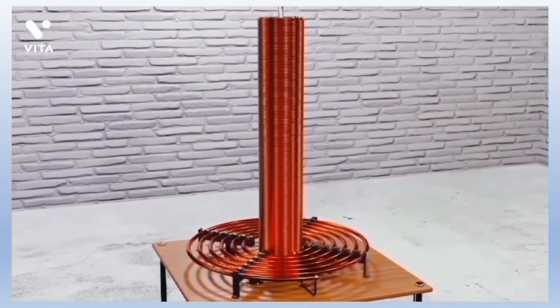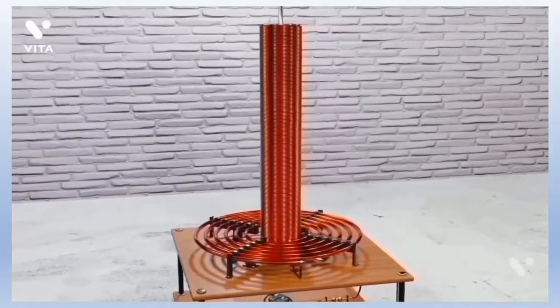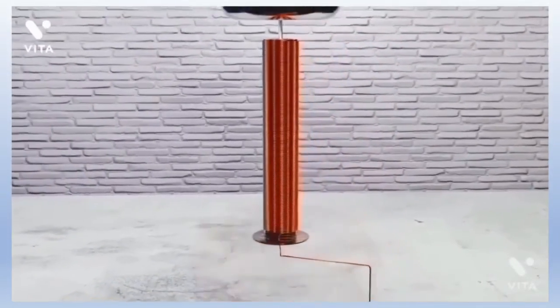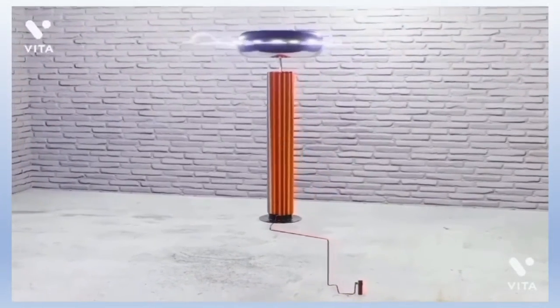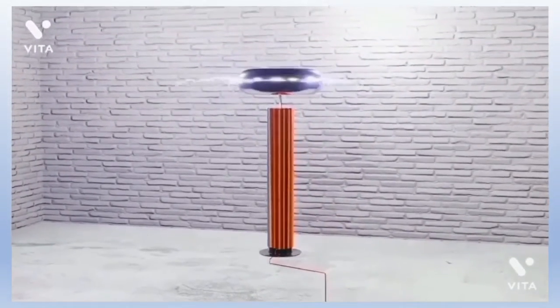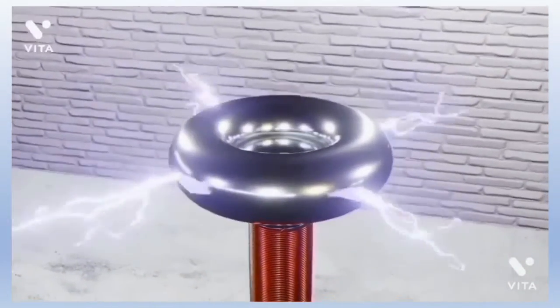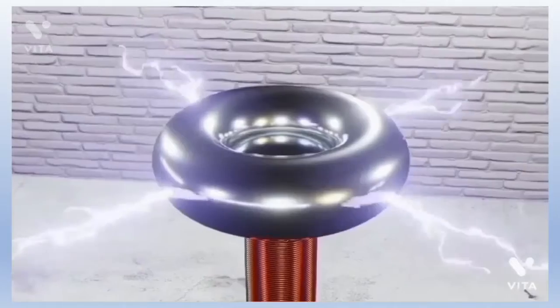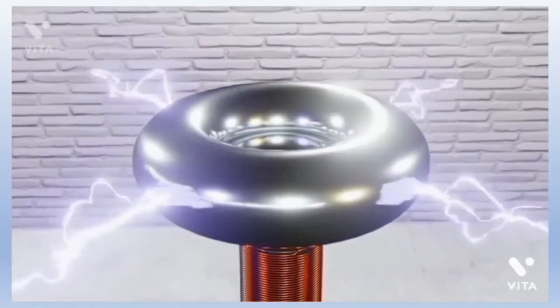This will increase the voltage in the secondary coil, which, by the way, if we analyze independently, is connected to ground, and in its upper part it has a metallic piece of toroidal shape. It has this shape mainly to be able to accumulate a greater charge and prevent it from escaping into the environment by the corona effect, and therefore also preventing the voltage of the assembly from increasing further.